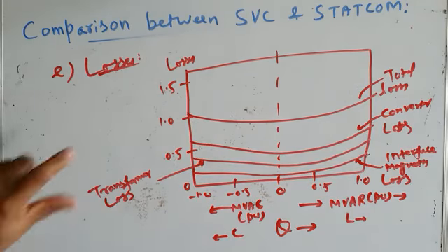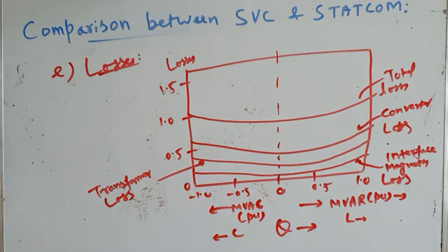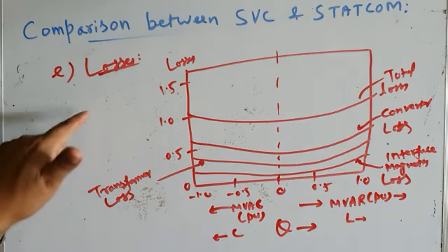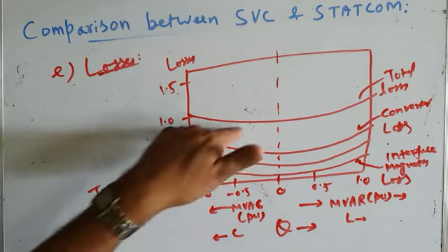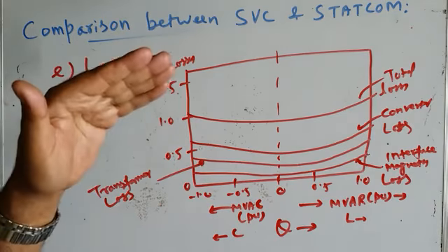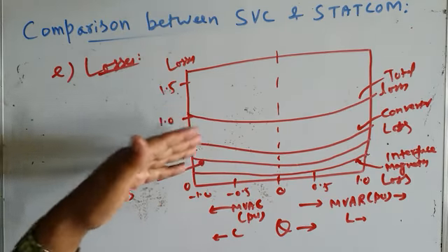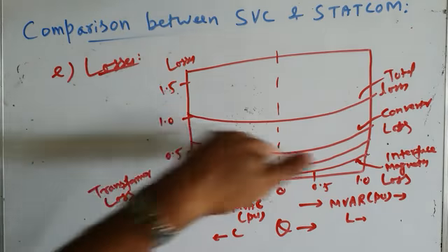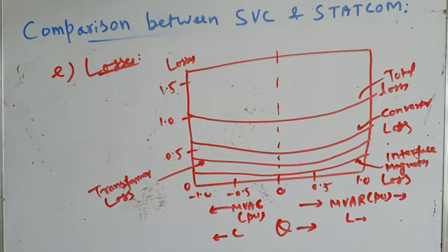However, at this time this goes in favor of SVC. Presently SVC has slightly less losses than STATCOM, but in future, 5 to 10 years down the line, STATCOM will have less losses than SVC, and therefore you will start replacing all these SVCs at all those locations where they are installed by STATCOMs. Okay, so this is about losses. And then